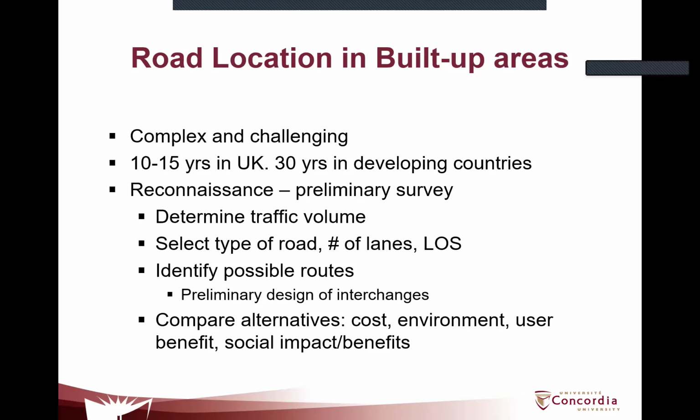So in a built-up area, you need to also consider the traffic volume. In a rural area, you can ignore the traffic volume and the level of service, but in a built-up area, no. If you go back to the first class, when we talked about the Highway Capacity Manual, we looked at the level of service for different types of roads.